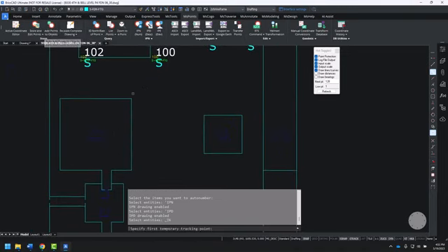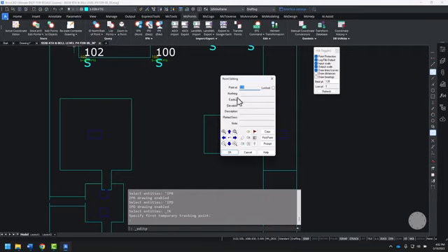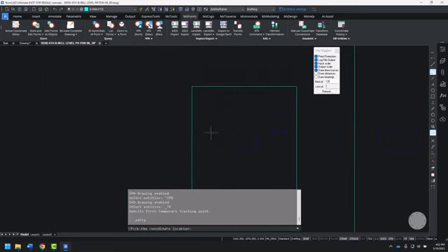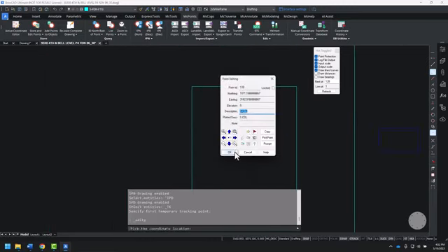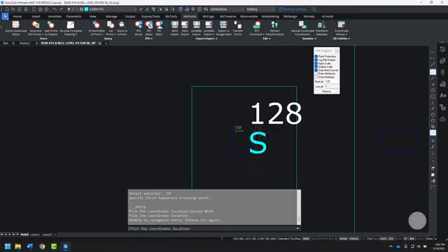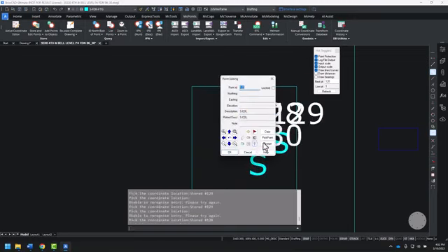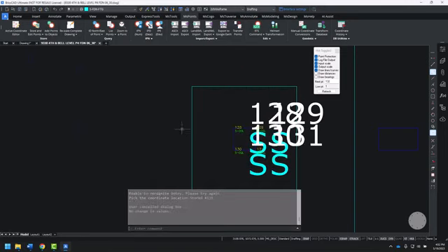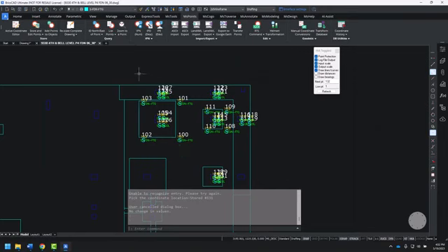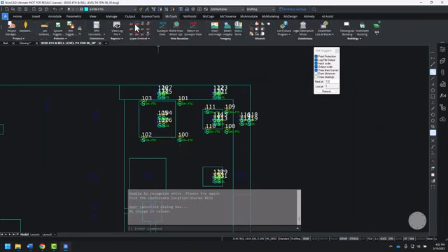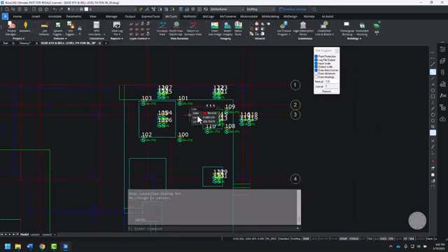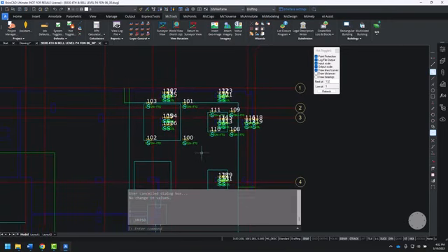To add additional points, I can choose Store and Edit Points, enter a description, S-COL, and I can pick a point. By using our entity snaps, I can add as many points as I like and where I like. I'll unisolate to get all of our layers back.